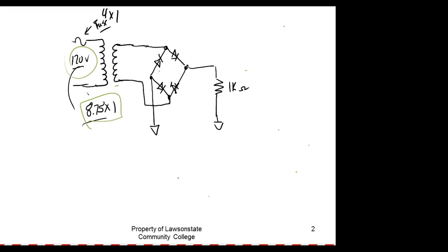So what we're trying to do is figure out if this is a negative or a positive supply. We look at the lead that's not common, and then I follow back this, and notice both sides are pointing back to the source with the anode, so this is a positive supply. So let's see how this works.